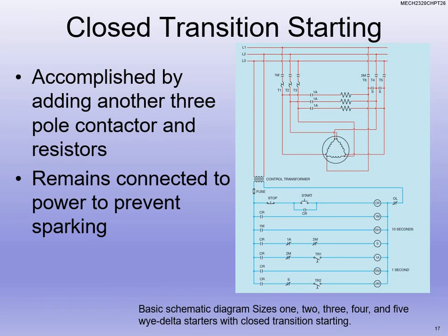All right, guys. Hopefully, we got a little bit better sense of why we would use a Y to delta starter, and understanding we're still controlling that inrush of current and the relationship of why we use the Y. We produce less current with the Y, where we control the inrush current, so we protect the motor, but then the Y is not strong enough to run the motor. We can switch back over to delta, but delta has too much inrush of current that can damage the motor, so that's why we have to use a Y to delta starter for this particular type of motor, to protect it and make sure that it operates where it needs to be.